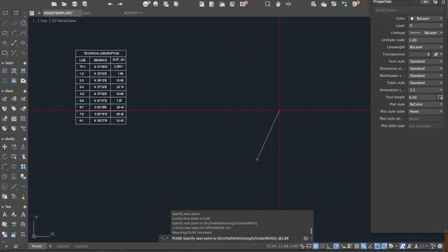Instead, place the angle icon or the less than icon, which is this one. And then now, type in the bearing. So you will start with letter N, and then the next one is the degree.